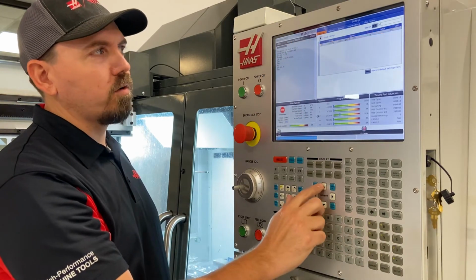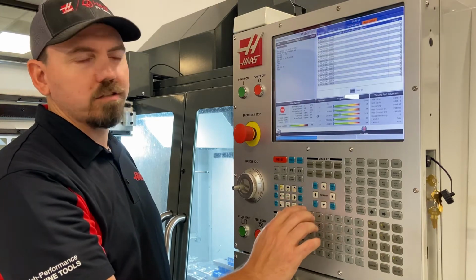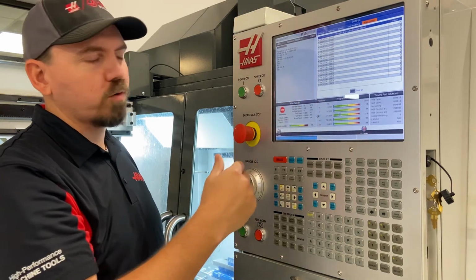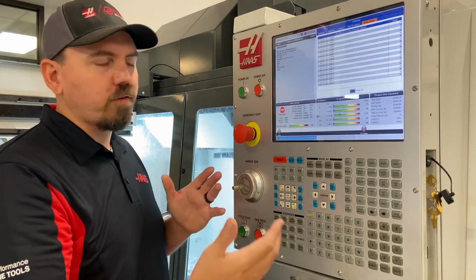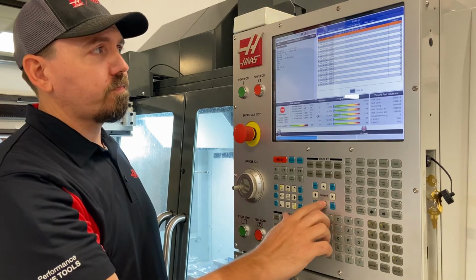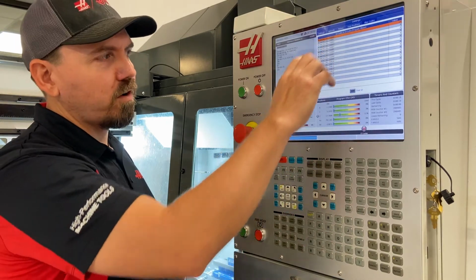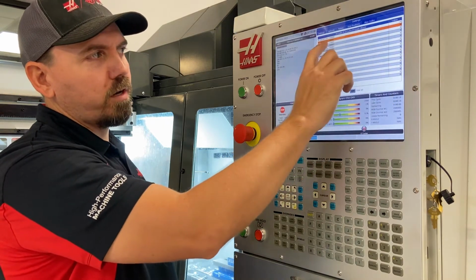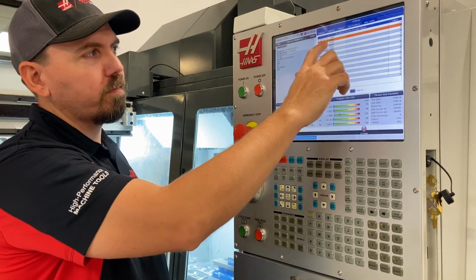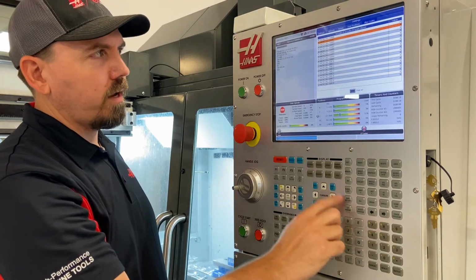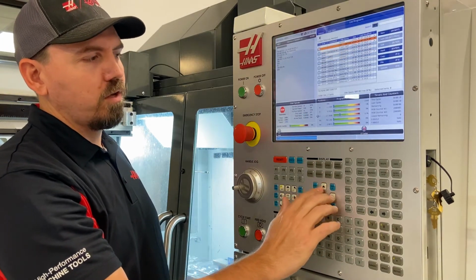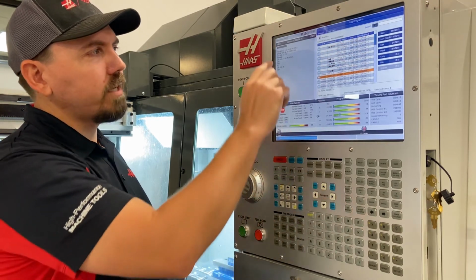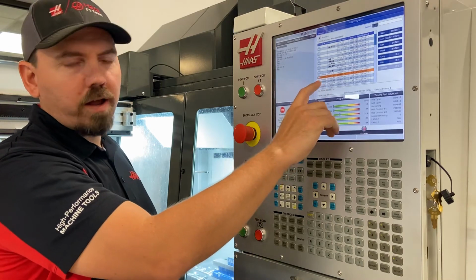In settings, from here I will cursor up and over to alias codes, and here I can choose to create my own M code or G code. In this case, we're going to convert an M6 into a different M code. I've already done this, so these numbers are already populated in here, but in this case I'm going to change my M6 to run an O9001 program. Okay, so in my list of programs I should now be able to go to the O9000s, and anytime an M6 command is run, the machine's going to run the O9001 program.